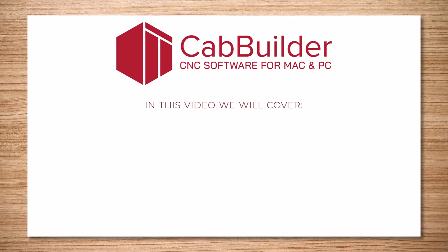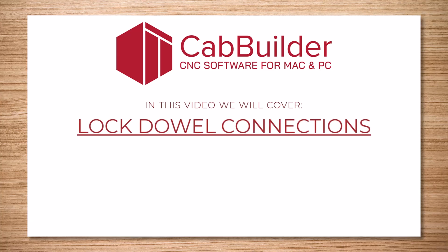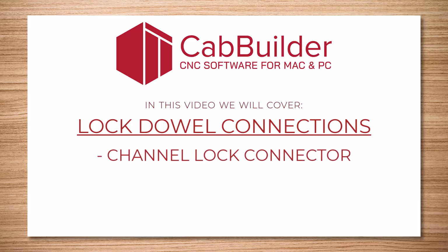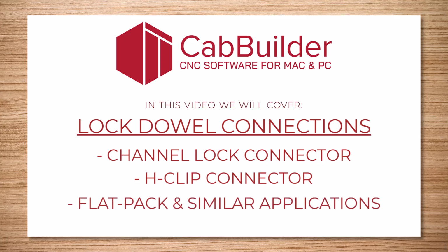In this video, we will take a look at how to create and configure lock dowel connection constructions in CAD Builder. CAD Builder's lock dowel template supports two connection types, channel lock and H-clip. Lock dowel connections are commonly used for flat pack and similar cabinet applications, but the two connection types use different machining and assemble in different ways.